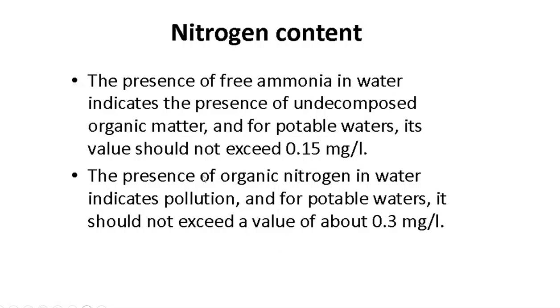So free ammonia should not exceed 0.15 milligram per liter, and organic nitrogen should not exceed 0.3 milligram per liter.